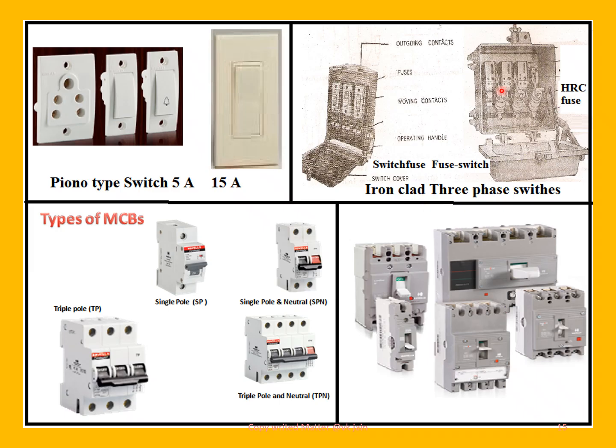Now these were of two different categories. This one is switch fuse unit, and this one is fuse switch. It is known as fuse switch because fuses, these are the fuses, HRC fuses, are provided on the switch handle. This is the switch handle, and the cover gets detached like this. It is hanging, not detaching.